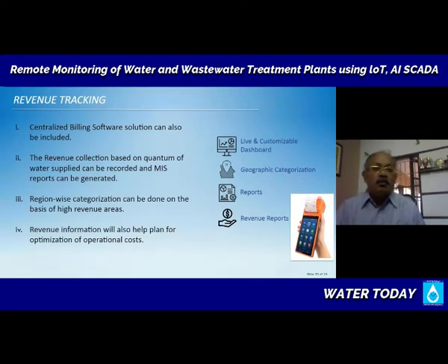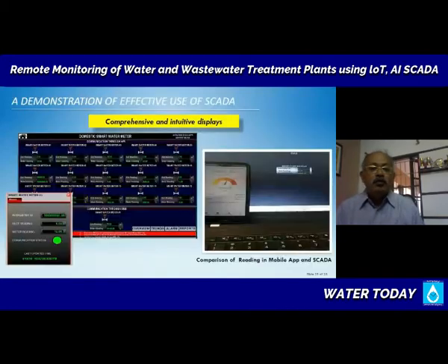And one other thing, when this is something that I use while addressing municipalities and all who go for individual consumer metering with these AMR meters, etc. Now, a municipality which was hardly having any metering to begin with now switches to several thousand meters that all need to be maintained. So, your systems have to be maintenance friendly. So, if a meter is not sending you data for 24 hours, for example, then you could generate a warning that this particular meter is not responding. It could be a meter failure or it could be a power failure at the metering location.